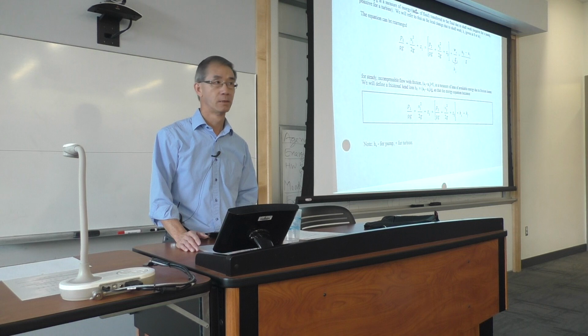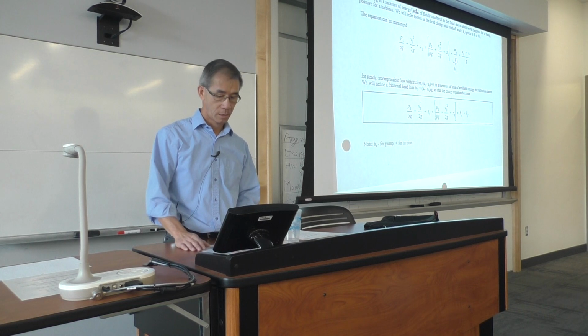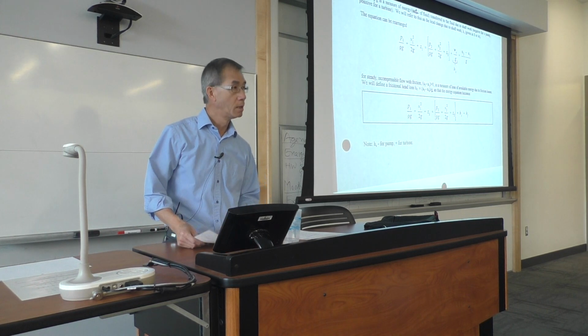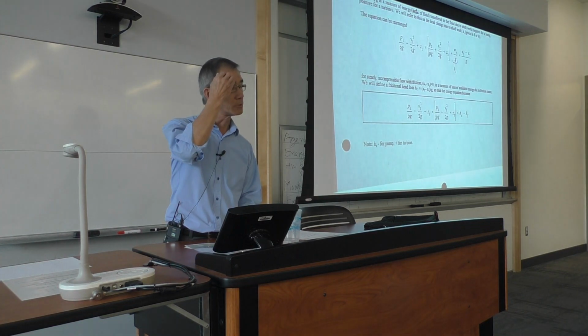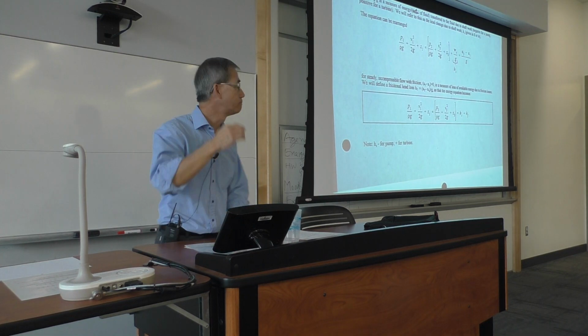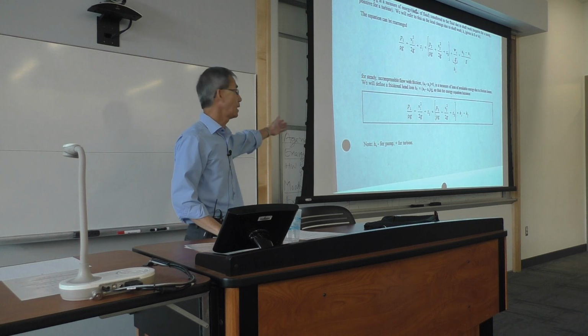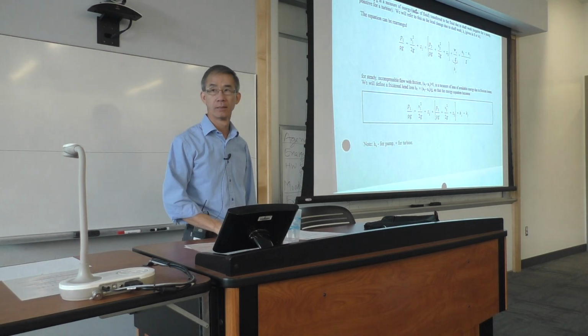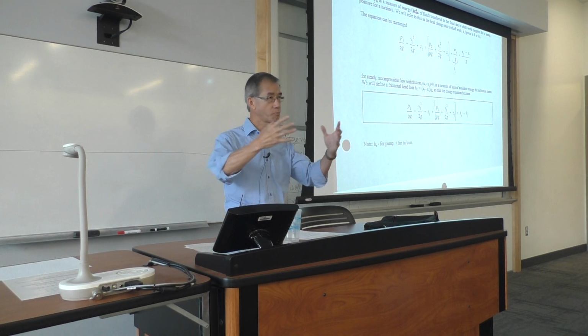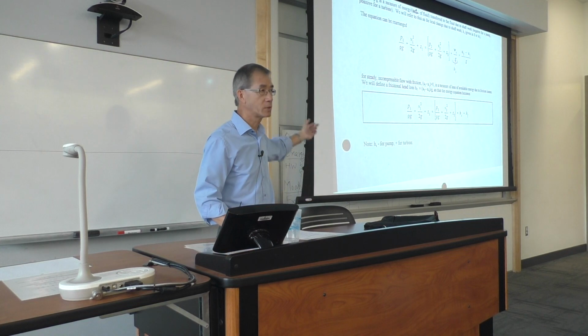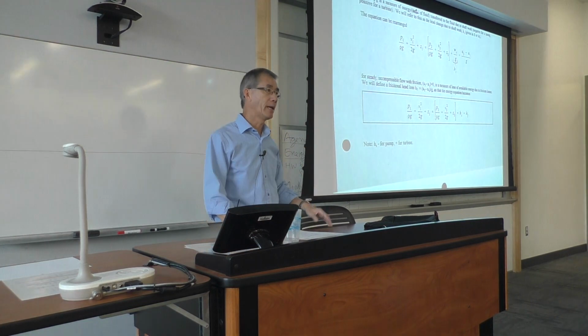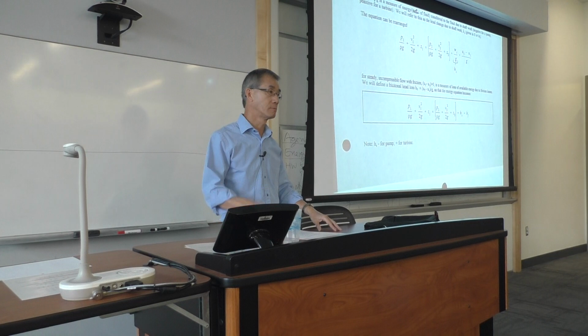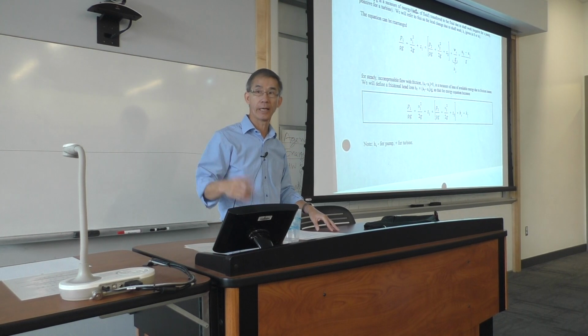Questions? Yes? Would you use the mass flow rate to translate the head into power? Yes, it's behind the screen. That's why I reminded you. When I pull up the screen, I will revisit that. The answer is yes. So the head, if you say I cannot put myself on the head, then you use that power equation, which is m dot, mass flow rate, times specific work per unit mass, which relates to the head.